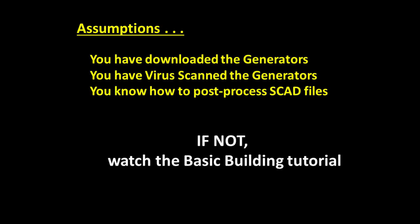Before we start on the generator, we need to make a few assumptions. We will assume that you have successfully downloaded the generator's zip file, extracted them, virus scanned them, and launched the flat roofing generator. We will also assume you have learned how to post-process the SCAD files through the OpenSCAD program to create stereolithography files. If either of these assumptions is not correct, please watch the tutorial on creating a basic building where these concepts are introduced.